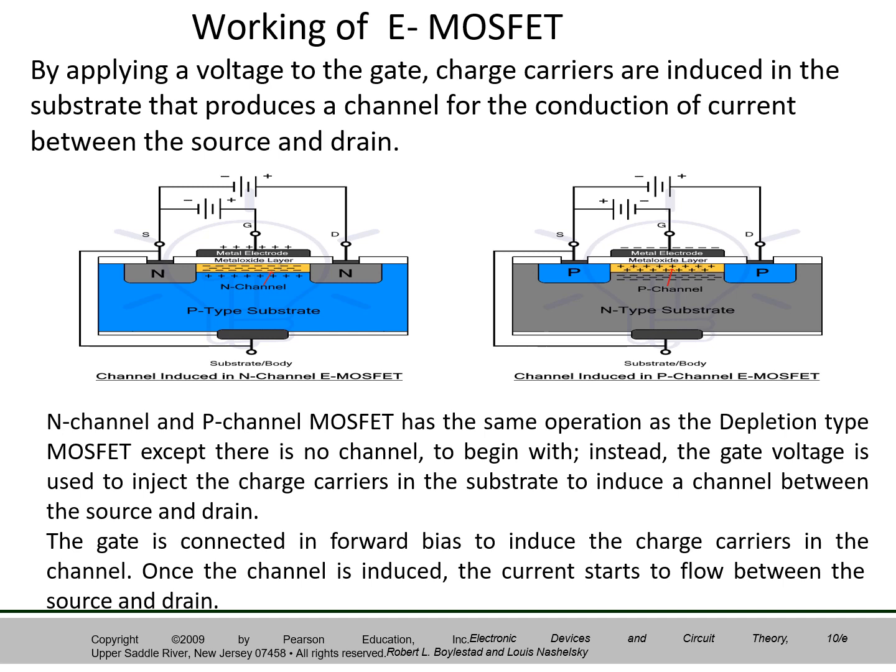When you give VGS is 0, current is 0. What happens when you apply VGS positive voltage and VDS positive? See here, the positive potential at the gate will repel the holes in the P substrate, which results in a depletion region near the silicon dioxide layer. However, the electrons in the P substrate will be attracted towards the positive gate voltage, and they accumulate in the region near the silicon dioxide layer.